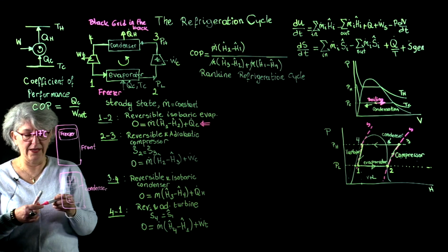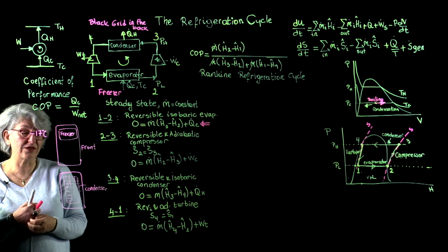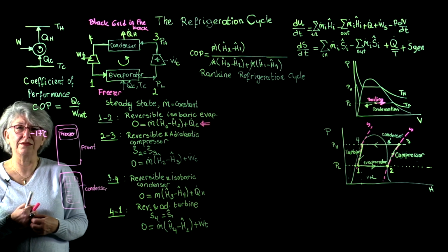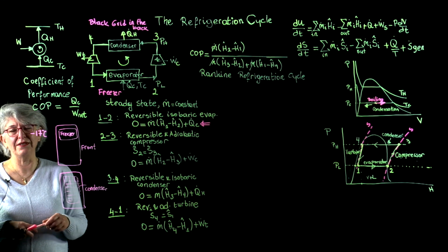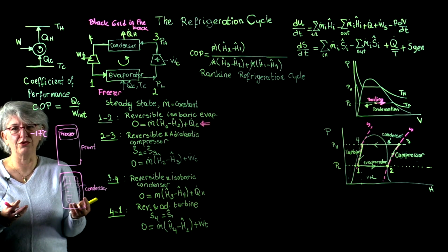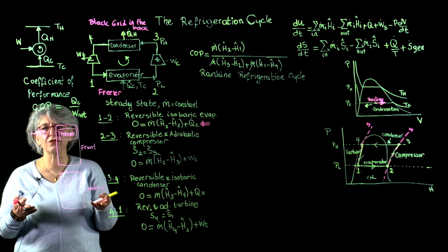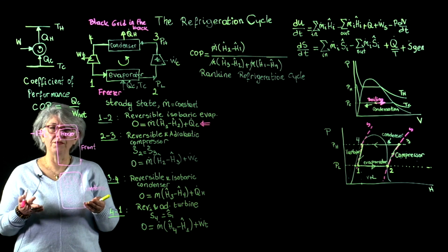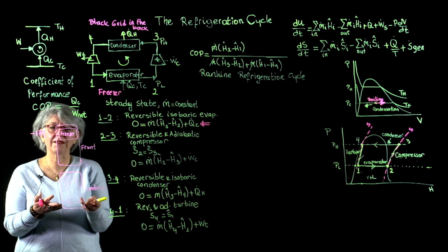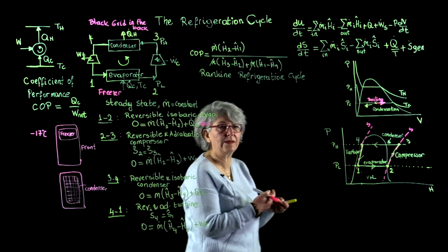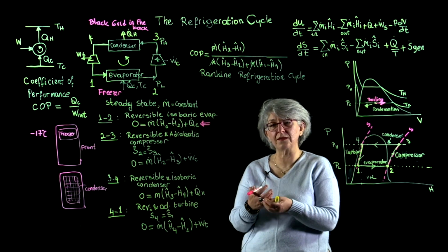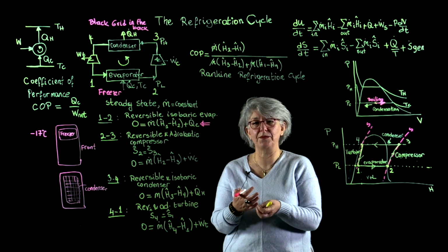All right? And the condenser is going to discharge to room. But the room temperature is going to change from season to season. So we need to design the system in such a way that it should be able to discard heat to possible very high temperatures.